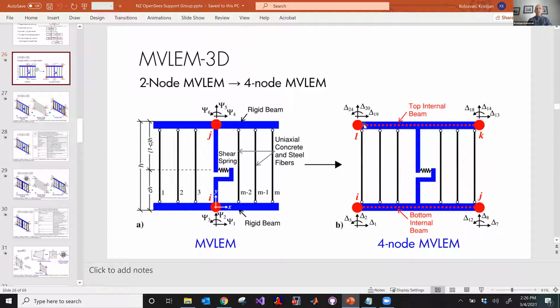Concrete CM, I can see that, right? Depends how big your model is, but Steel MPF really shouldn't give you any convergence problems. In fact, I modeled this whole tall building with Steel MPF in it, so maybe together. I don't know which component the convergence problem is from, but I believe it's because of Concrete CM, because it's a very complex model. I think the source code has like 1,000 lines just of the different hysteretic rules. So it's fairly complex.